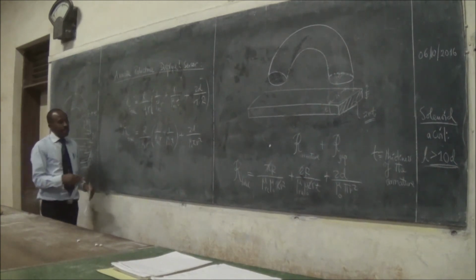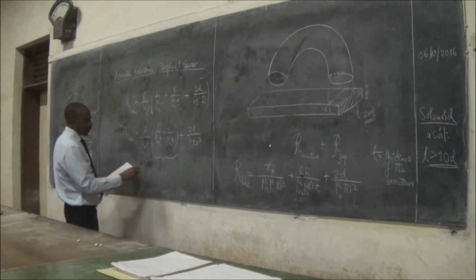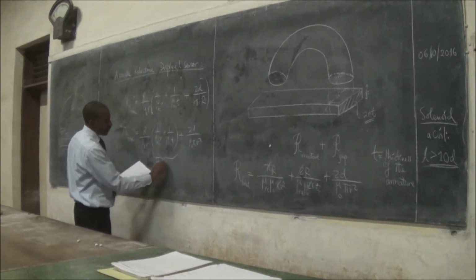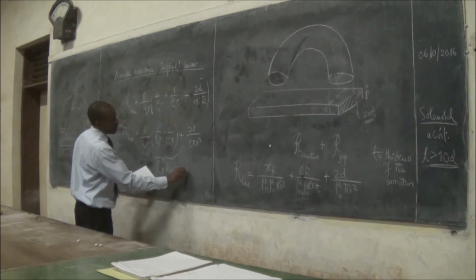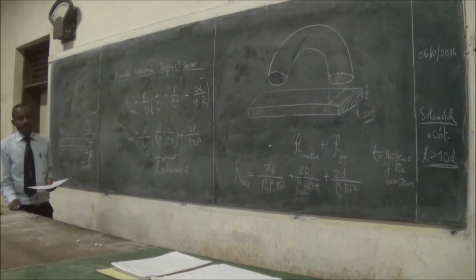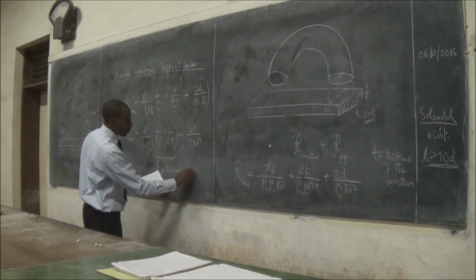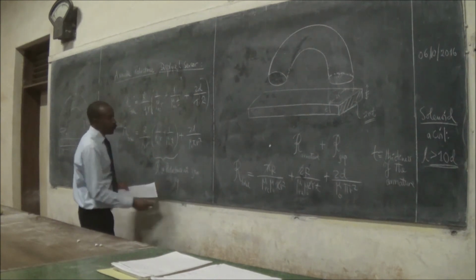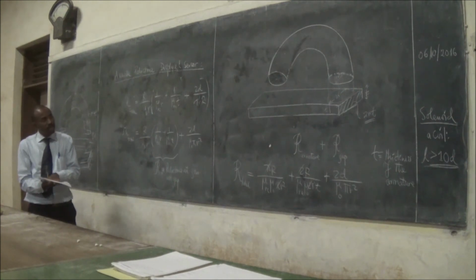My reason for doing that is that this one now gets a new name, the reluctance R naught, which is the same as the reluctance at 0 air gap, when you have the armature touching the torus.